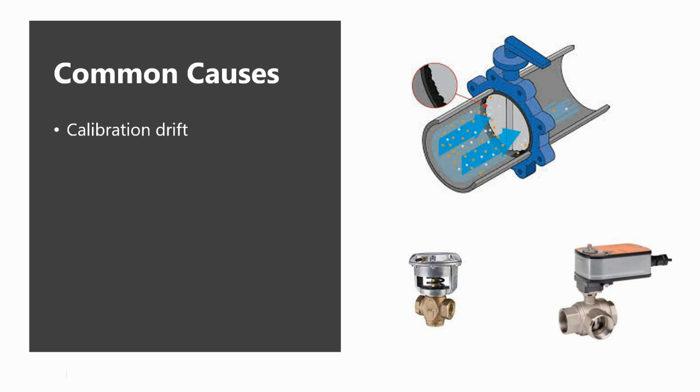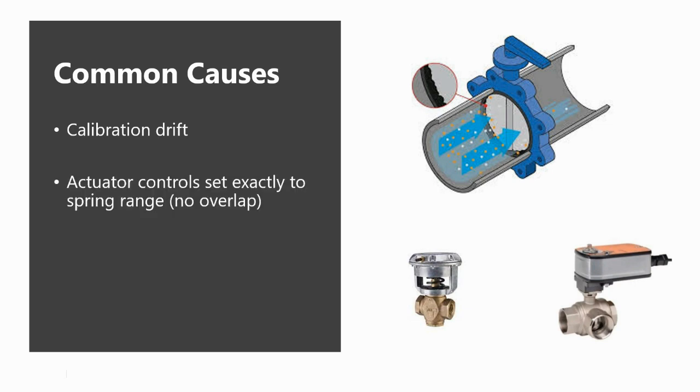Then in DDC to pneumatic hybrid systems, the DDC's electric to pneumatic transducers are notorious for drifting and needing frequent calibration. So whether it's by means of pneumatic or electric control, the span of the control signal to the actuator is critical. It needs to be specifically set up for each individual valve, because manufacturing tolerances can affect the actual operating range. Just because it has a specified spring range or voltage range doesn't mean it will open fully or completely close with exactly those values listed for it.